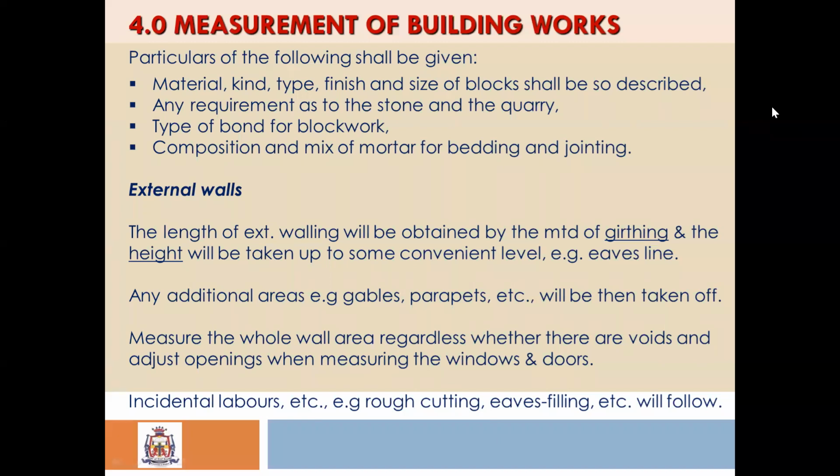So you measure the whole wall area, and this time when you are measuring, people make a mistake. They normally ask the same questions. The doors and the windows and any other openings are assumed not to be there. Let me use that term. So when you are handling the walls, you take it as though it is fully a wall. As you'll see in the notes that will follow, things to do with the windows and doors, those are deductions that come in later.